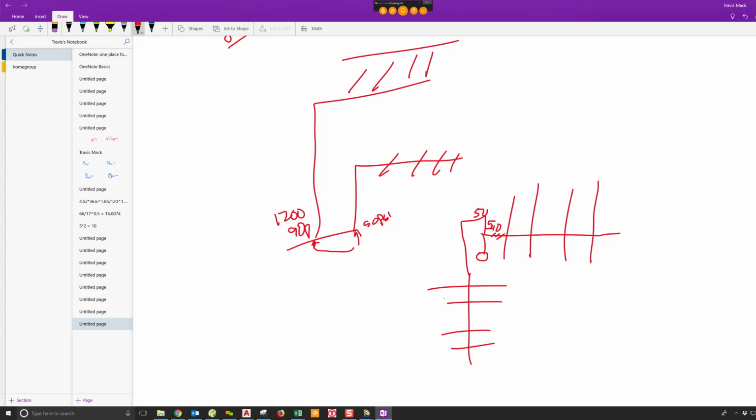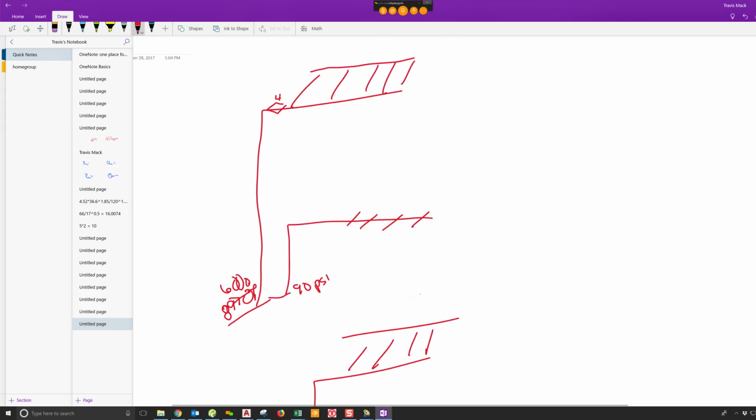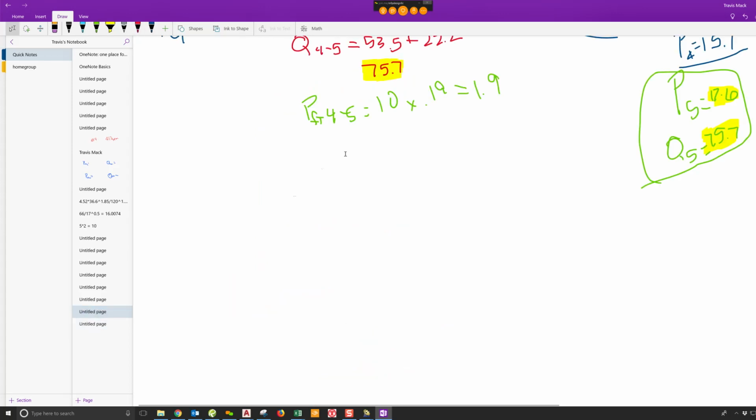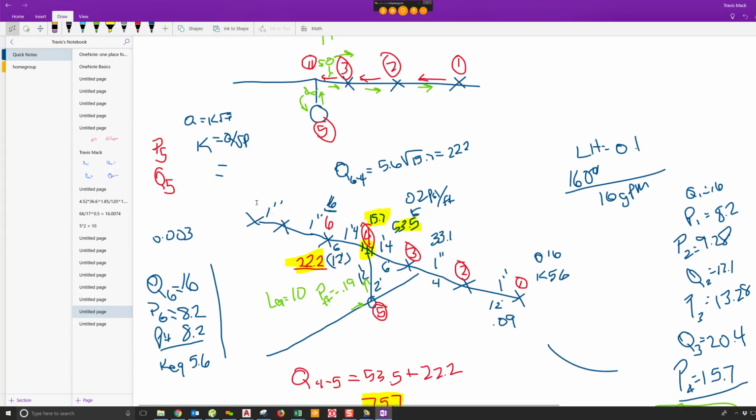Does that make sense? That's a hard concept for guys to grasp. That whole balancing and smaller pipe is sometimes better. That's a hard concept to grasp. But if you understand this thing that we did right here, if you can understand this, you'll know calcs better than 90% of the guys doing design today who are just plugging in bigger sizes to make things work. Understand that there, and you guys will greatly improve what you're doing.